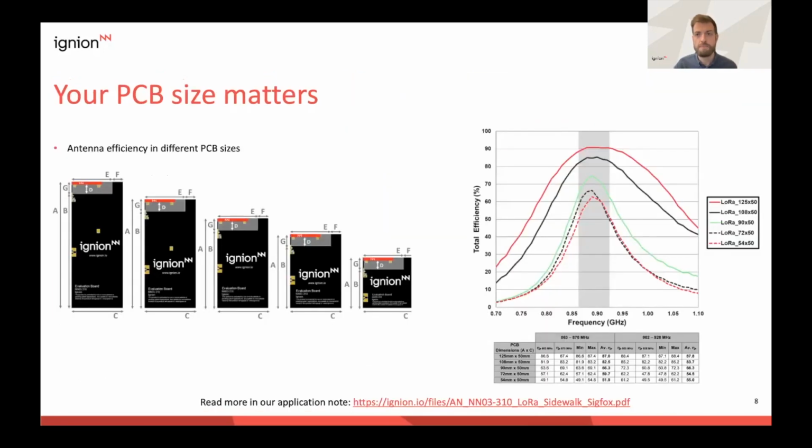And when you're designing your next device, I want to make sure that you consider that your PCB size has an importance for how high efficiency you can get on your RF system. This is true for any integrated chip-like antenna, where the bigger the PCB size, the higher the efficiency you can achieve.